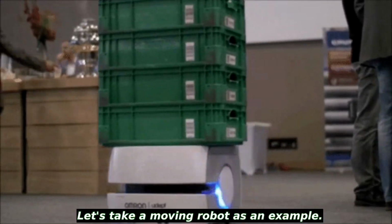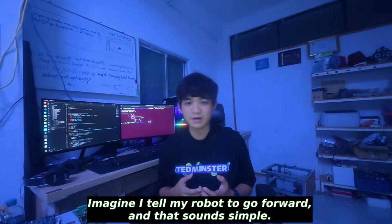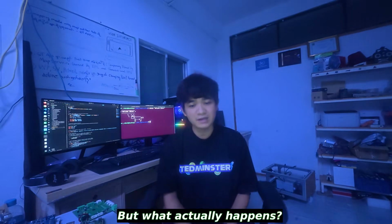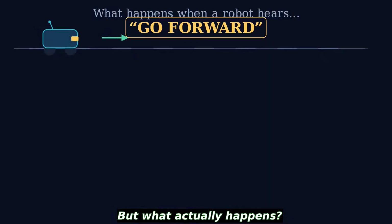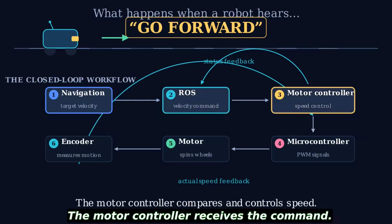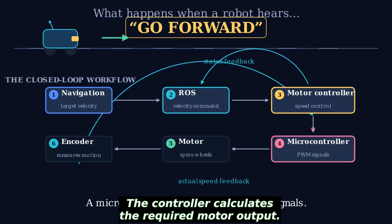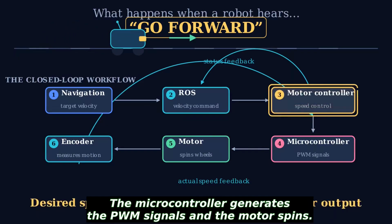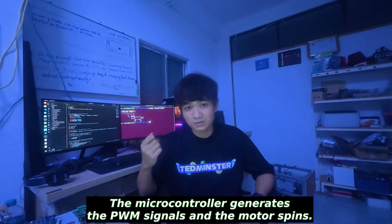Let's take a mobile robot as an example. Imagine I tell my robot to go forward, and that sounds simple. But what actually happens? The navigation system calculates the velocity and processes the velocity command. The motor controller receives the command. The controller calculates the required motor output. The microcontroller generates the PWM signals and the motor spins.